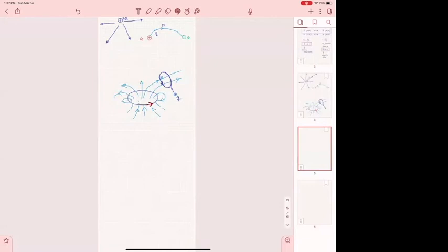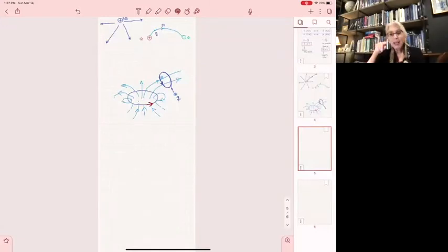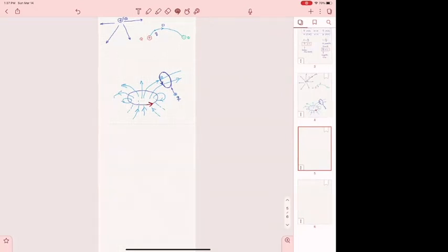So that's for part one. For part two, it asks for the total flux through the area of the small circle. Okay, so in that case, to be able to find the total flux, you have first of all to go from H to B. And B will be H multiplied by a scalar. So you will have to be careful about that product and the units. And then you have to integrate B to find the total flux. Right. Yeah, okay, I get it. Thank you so much, Professor. You're welcome.